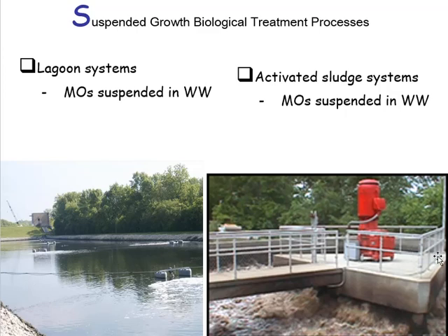There is another method called the activated sludge system. It is a modification of the lagoon system. Generally we use it in the cities, and we make big tanks, and the wastewater goes here. We provide mixing with a fan, and more oxygen will be dissolved. Bacteria will remove the organic material fast. Again, the microorganisms are in suspension. This is the biological treatment.